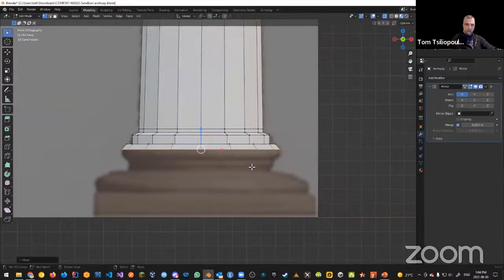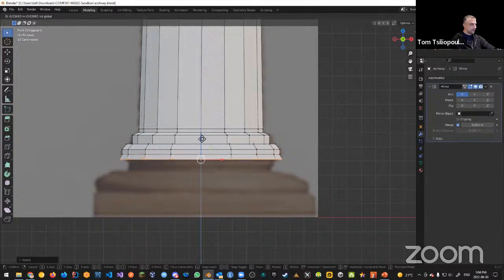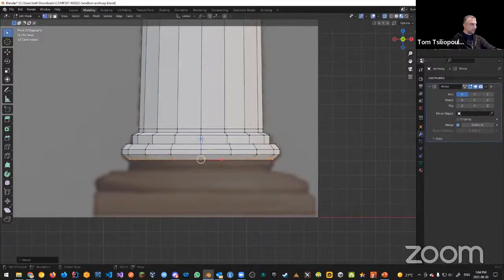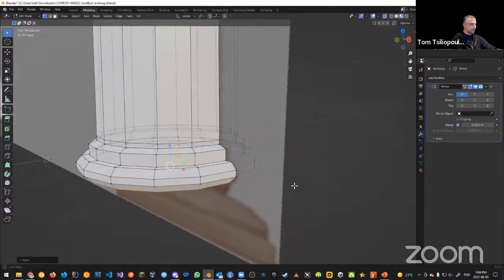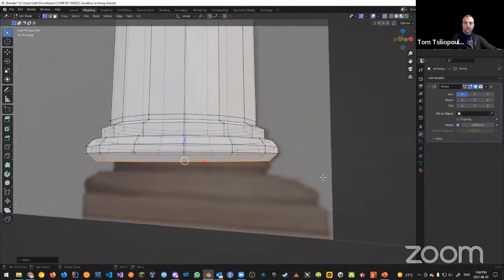You can also use beveling if you really want to. I'm just going to use this right now. And then I want to extrude. I want to push it down here to about this point. And I want to extrude and press enter. And then I want to scale so that it's a little bit bigger. And I want to push it down, right, like this. And then I want to scale in so that it's like this. You can see that I can create the shapes that I want with basic movements. So again, when you're looking from the side, it's something that looks like this now, right? All I'm doing is extruding, scaling, extruding, scaling multiple times.